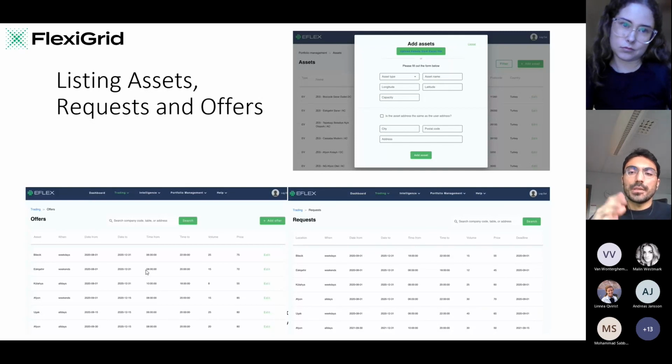If we limit the capacity before the market is cleared on the day-ahead energy market, then this capacity limitation can be shared and coordinated with the TSO going upstream, so that the TSO knows how much flexibility from the distribution networks will be available at different distribution regions. But it's a tricky thing to solve, I can agree.